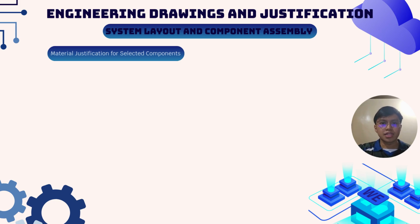Moving on to our engineering justification, the selection of material for this conveyor system was driven by three critical requirements: fatigue resistance, vibration damping, and tensile strength. Our goal was to ensure a long operational life while maintaining high precision. For the drive shaft, we selected AISI 1040 cold-drawn steel with a yield strength of 490 megapascal. It provides the necessary endurance against the constant bending and torsion the shaft faces during operation.